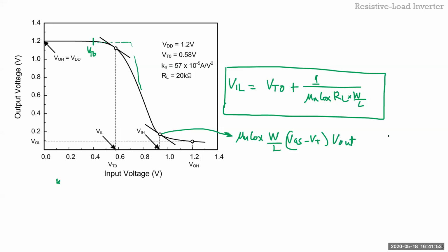You can use this equation just to approximate it. And that should be equal also to (V_DD minus V_out) over R_L, right? This will be a little complicated because when you take the derivative, you'll still get a V_out term, because now you've got a times V_out.